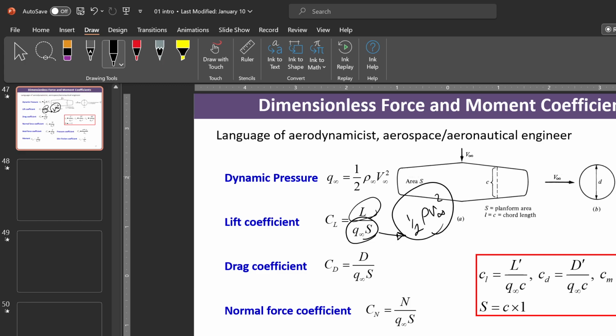There are a couple of things that are a bit different, like the moment coefficient. You have to include a moment arm as well, right? Moment is force multiplied by an R. To find the dimensionless coefficient, we divide the moment by the dynamic pressure multiplied by your area and the length. It gives you a representation of the kinetic force in your system multiplied by the arm. Do you have any questions?